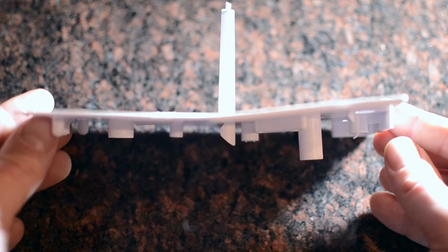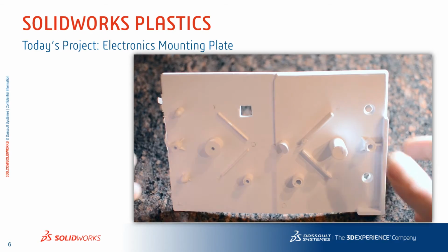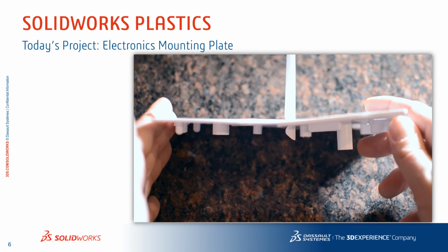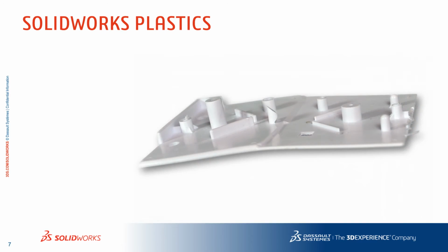You can see there's some out of plane warpage or potato chipping. And overall, it's not the type of part that I would like to receive back. So this is an electronics mounting plate, and let's see how plastics helped us analyze and correlate to this physical part. Let's also talk about what we could do differently from a design standpoint before we even get to manufacturing.